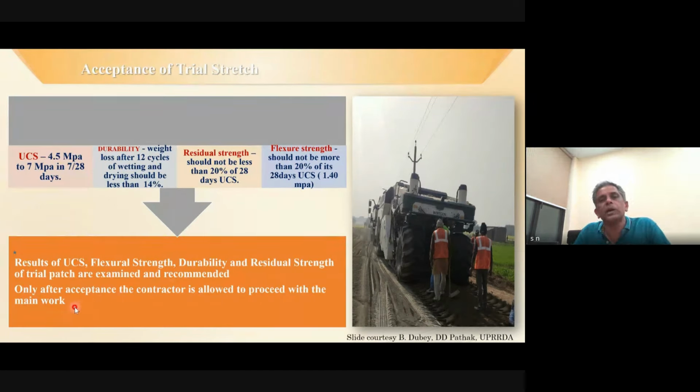The advantage you have here is that, let us say the strength is not meeting the requirement, you can do checks in terms of the cement content, and we will discuss that later. It could be an issue with the cement content put in there, or the spreading of the cement is not uniform. The sampling you have done may have been in a location where the cement quantity was less, and it ended up having a lower strength than required. That could be a possibility.